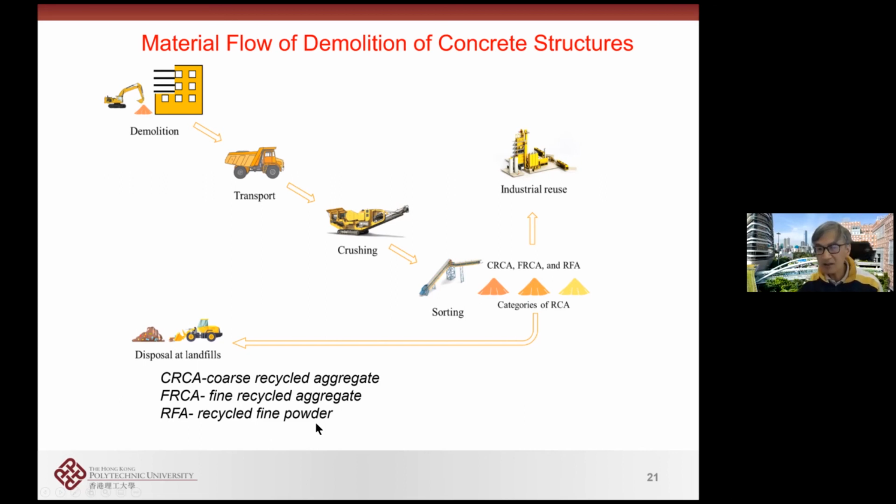And the fine powder is the most problematic for the recycling industry or for the concrete industry, because if you have too much fine material, it cannot really be used in concrete. The fine material is actually treated as a contaminant in making concrete, because the silt takes up a lot of water, making workability very, very difficult. And this is the most problematic material.